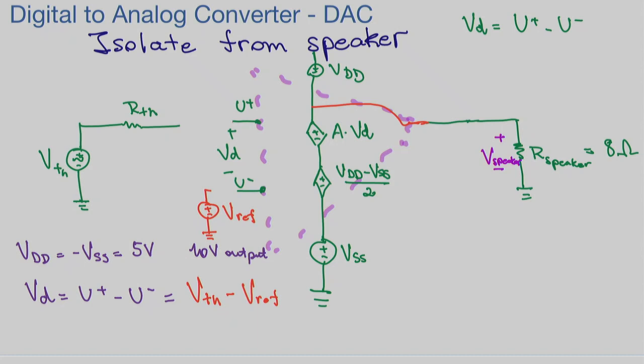And then, what's the current flowing through an open circuit? Zero. So there's no voltage drop. If the current is 0 in this node, then I know that the voltage here is the same voltage as that node. Excellent question. Thank you so much for that.